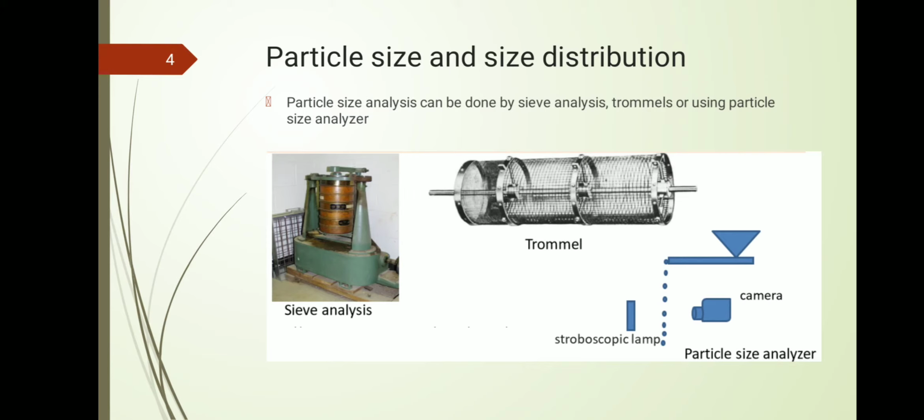The sieve is used in civil engineering laboratory, the geotechnical lab. We have different filters of different sizes. So our biomass will be put into this and it will be stirred. After stirring, it will settle in different layers of these filters, and each layer has a particular mesh diameter. So using that we can identify the particle size and distribution.